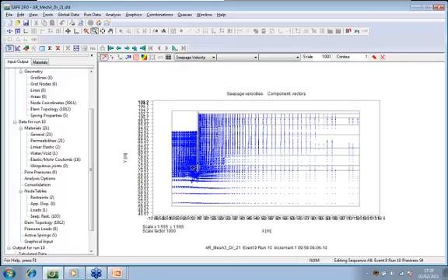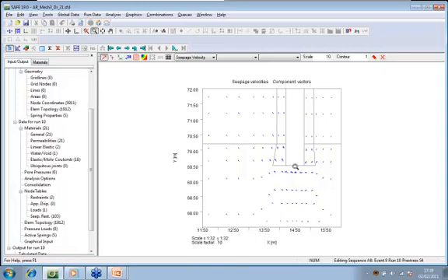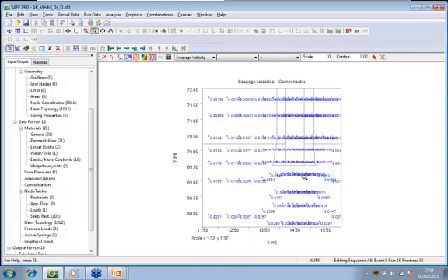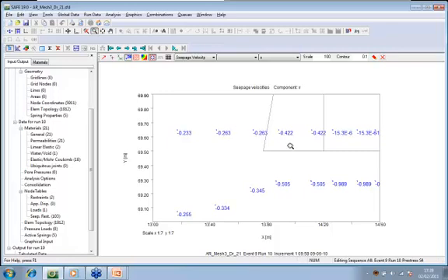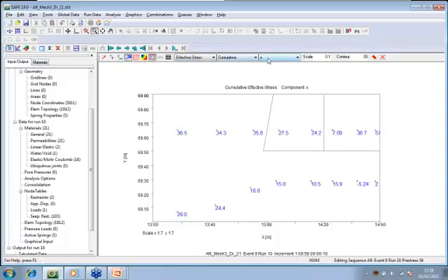You can see how the seepage velocity might change. So if I zoom in at the base of the retaining wall, I can see how my seepage velocity will change here. I can see what the actual number of seepage velocity is. So say, for example, in terms of numbers, I can pick out displacement, I can pick out the stress. And say, for example, if I want to look at effective stress, I don't need to look at the effective stress in the X option. I can look at it in the Y option. The major principal effective stresses, the shear stresses, the percentage of stress mobilized.